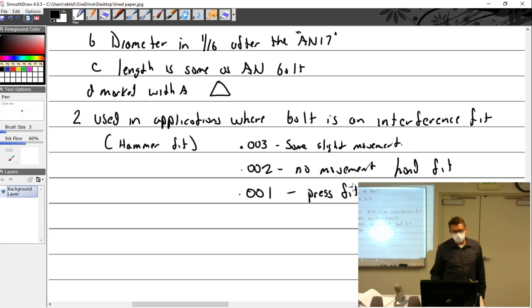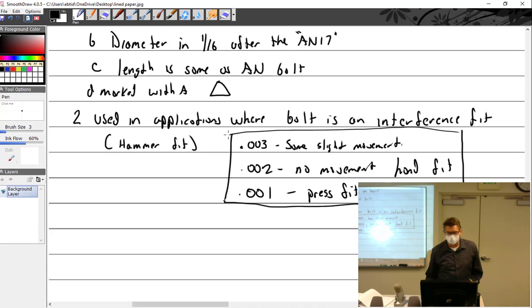And then when you get into an interference fit, that actually means that the part that is going in is literally bigger than the part that it's going into, which is going to have to displace some sort of metal. So that's technically what, to me, an interference fit is. But this is just kind of a side note, if you will, based on my experience in the machine shop. So you didn't have to measure stuff sometimes. You could just put it in and go, oh, that's about 2.5. And then you'd measure it and, yeah, that's about right.